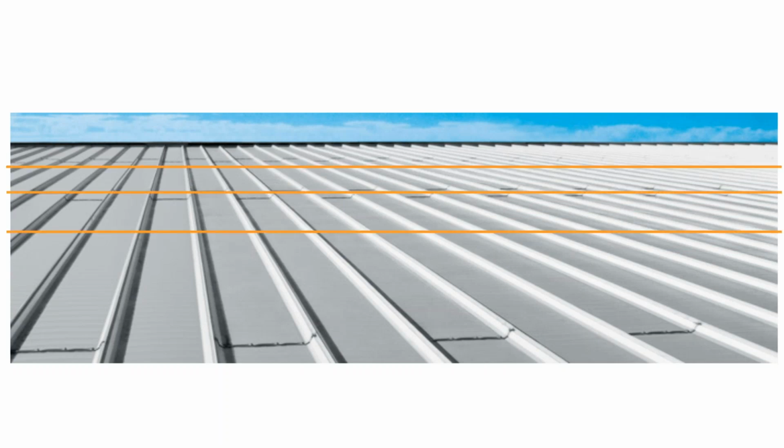Underneath the roof are these structural submembers, purlins, that span between frames, and those purlins are typically Z sections, singly symmetric. And the standing seam roof is connected with clips, and those clips are spaced a certain distance along the purlin. The purlin can be multiple spans. The connection point on the purlin is eccentric to the shear center of the cross section.